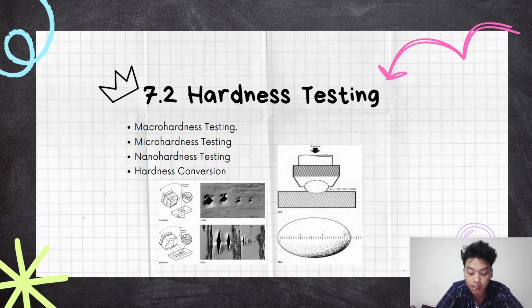Brinell test. The setup for the Brinell test is shown in picture 7.5a, on the right side. The indentation is measured in millimeters, shown in picture 7.5b. A hardened steel or carbide ball, 10 mm or 0.4 inch.